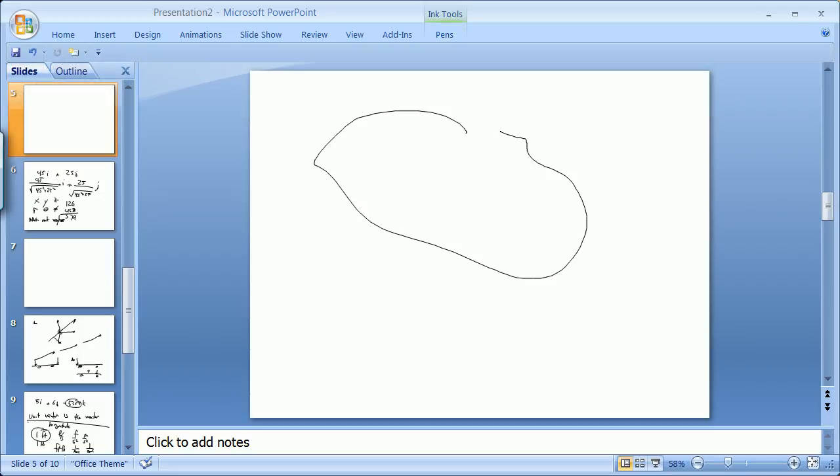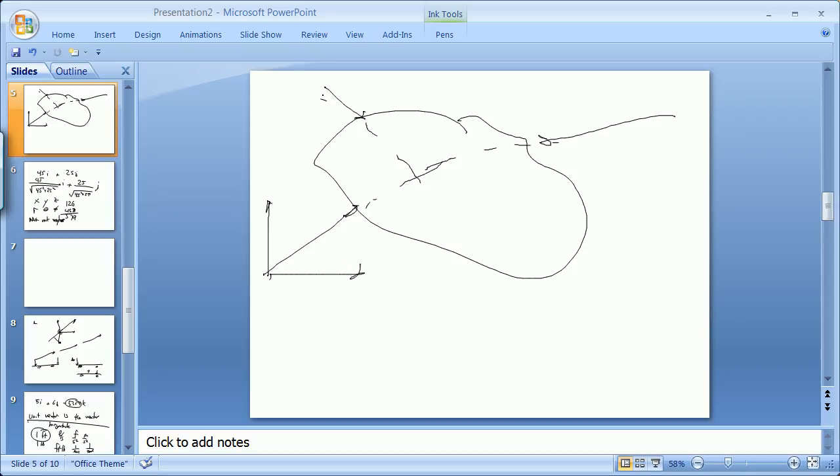It was a mass, if you would, with a set of forces here, here, here, lined up to be a concurrent force problem. And so how do you need to do that? Well, you just basically scale off your x and the y, scale off your x and the y, and scale off your x and the y. You make a table, force 1, force 2, force 3, your x and your y, and you add them up. That's a great way to do it if you're doing a concurrent force problem.